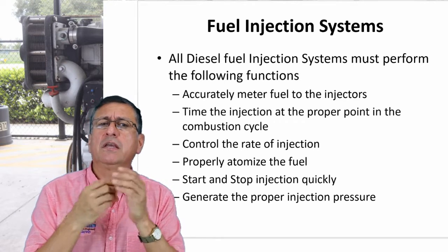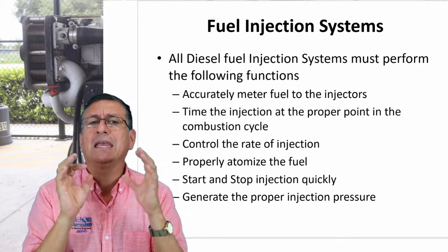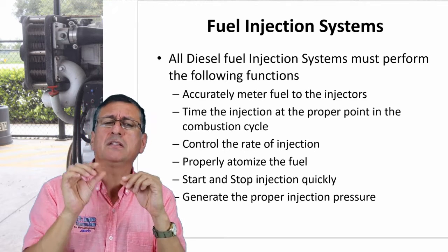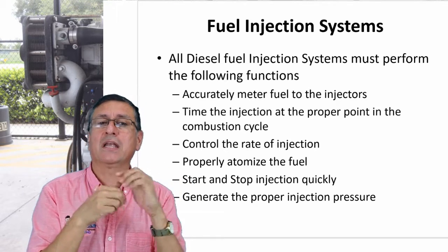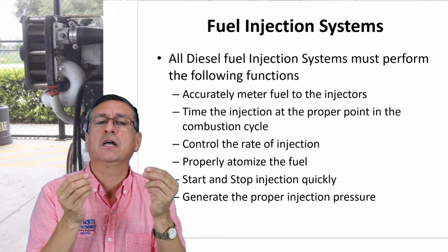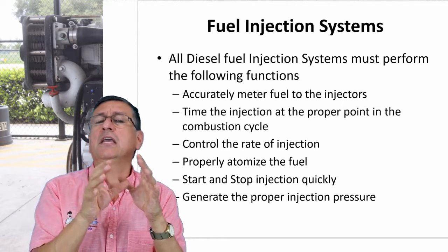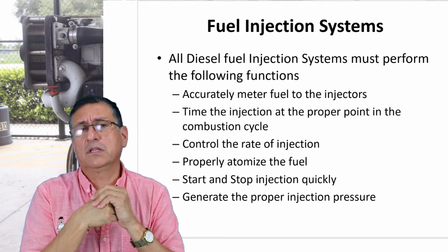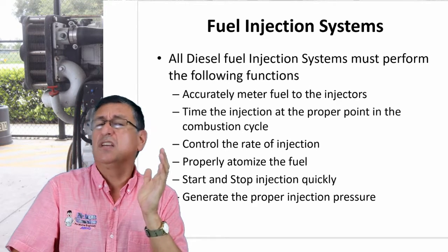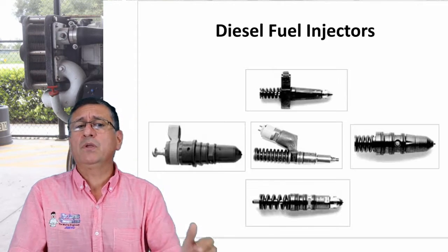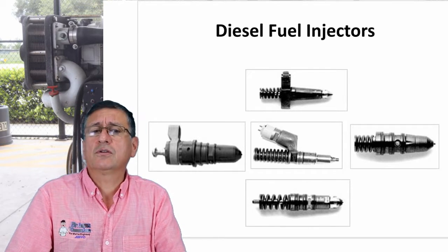If not, I recommend sending the injectors to the machine shop. They calibrate the injectors, they replace the spring, they replace the washers. I'm going to show right now where I located those springs and those washers, and they do the service and return the injectors properly calibrated. It's not expensive. What happened with the diesel fuel injectors?